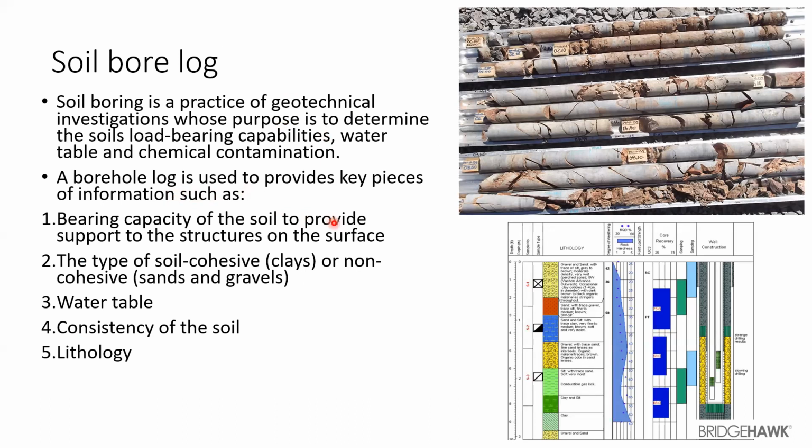So a bore log is typically used to provide key pieces of information, like what is the bearing capacity of the soil, the type of soil, is it a cohesive soil, is it a clay soil, a silty soil, sand. It will tell you about the water layer, the consistency of the soil, where is the rock, where should be your founding level. It will basically give you an idea of the lithology.